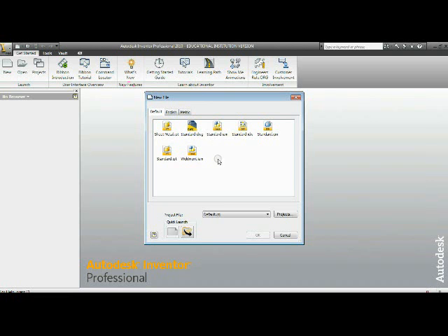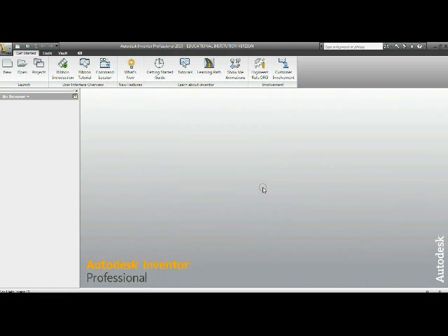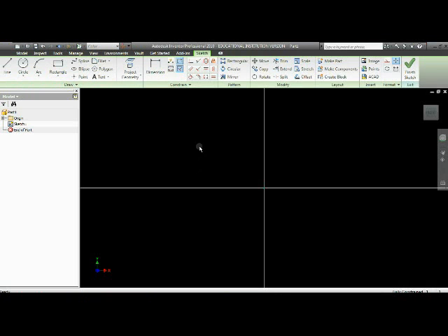And then we have standard.ipn, which is a presentation file, which will basically allow us to take that 3D Inventor assembly model and do like an exploded view type drawing and be able to show how things all fit together. So for now we just want to hit the standard IPT. Now you can either double click that icon, or you can click it and hit OK, and it's going to open up.